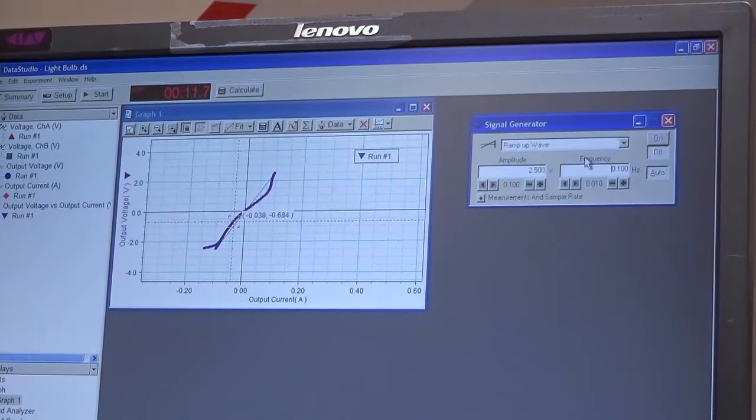If you have a low frequency being applied to that light bulb, that voltage is being applied in a very interrupted manner. So in that case, the light bulb, which consists of a tungsten filament, as we have seen before, is not going to get hot enough to reach its maximum operating temperature, for which that light bulb would be constantly glowing in a white light. Rather, that light bulb is going to be flickering on and off. So for a low frequency, you are going to have a constant change in temperature.